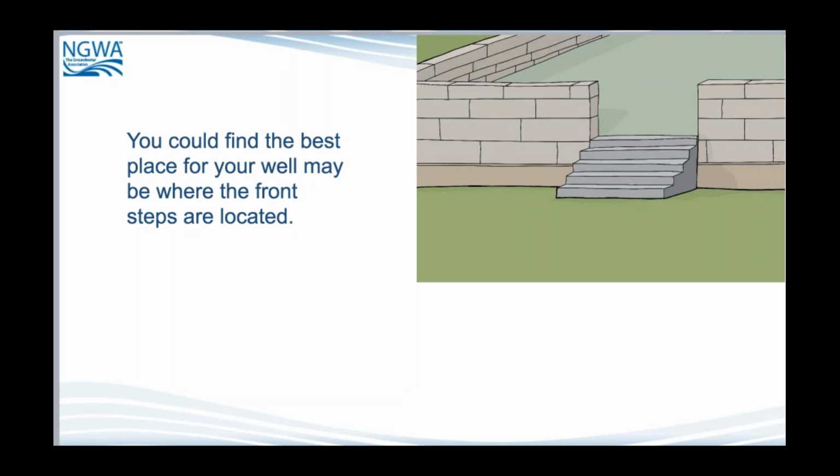There's been situations where we've had a developer of a subdivision where he was putting in hundreds of lots. He placed all the wells where he thought it was going to be the best, and one of them ended up right in the middle of the street that they were going to have to place. And there was no way to move the street at that point in time. The well had to actually be abandoned, take everything out of it, refill it with bentonite from the bottom all the way to the top, seal that well off, and then we moved the well over into an actual lot so that it wasn't in the middle of the road.